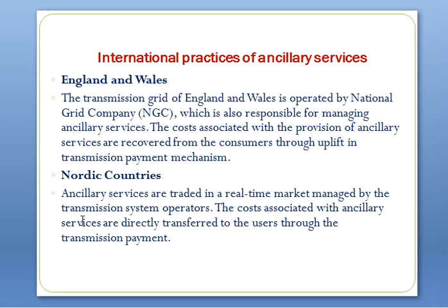In the Nordic countries, ancillary services are traded in a real-time market managed by the transmission system operator. The costs associated with the ancillary services are directly transferred to the users through the transmission payment. The voltage control. The local provision of voltage control and reactive power is mandatory for all the system generators. A response time of 5 seconds is required and the service must be supported for the period that is needed.